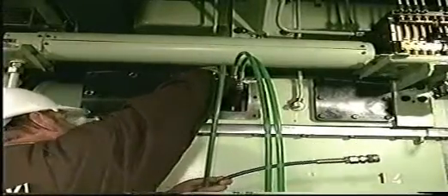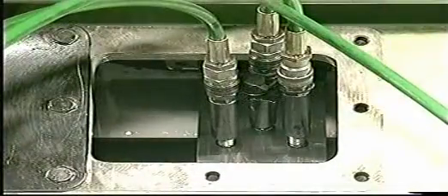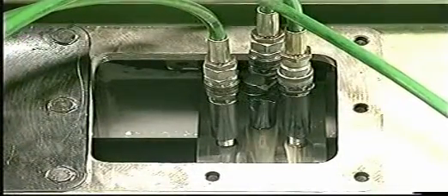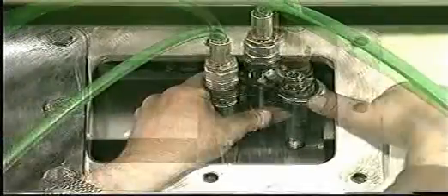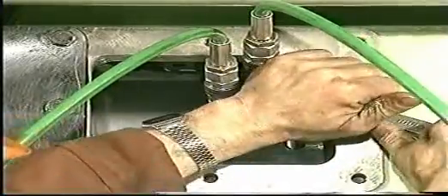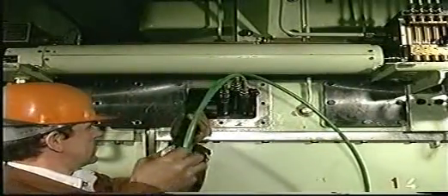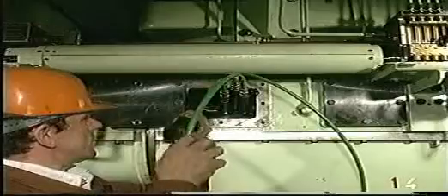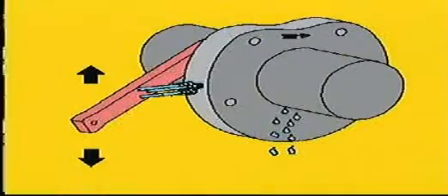Connect the snap-on couplings to the high-pressure pump and vent the system. When oil without air bubbles flows from the couplings, fully tighten the couplings. Turn the engine until the special spanner can be mounted, then raise the pressure until oil seeps out between the cam and camshaft.